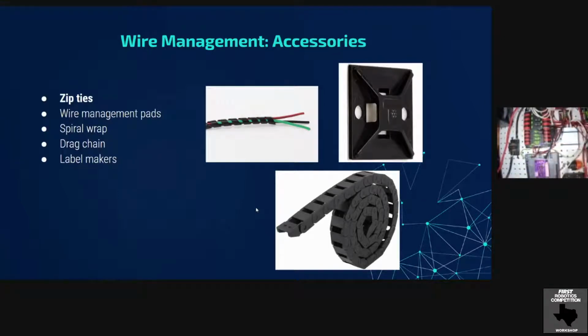However, I do know a lot of teams that have had great success with a radio holder. If you make it so that it's got hinges or something, like a door on the front where you can open it up, that's fine. That is something that you could actually bolt on, because your radio still comes out really easy. You really just want something that you're easily going to be able to remove and reattach, which is why zip ties are nice, because they're consumables and they're cheap.